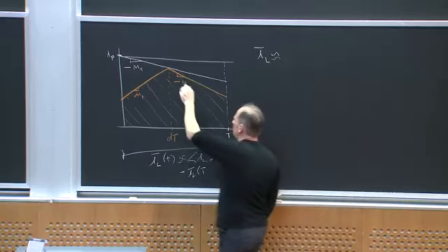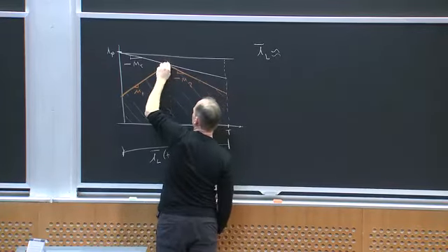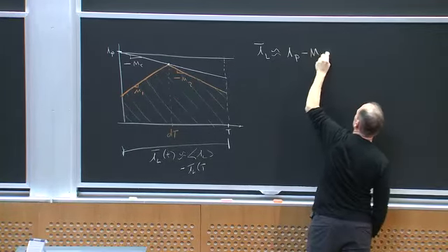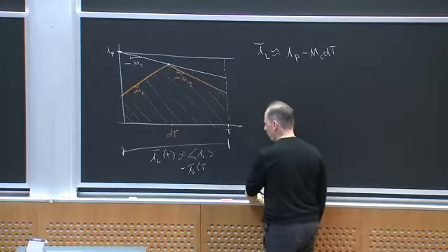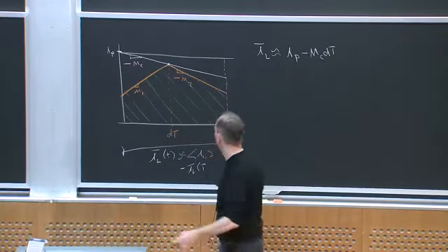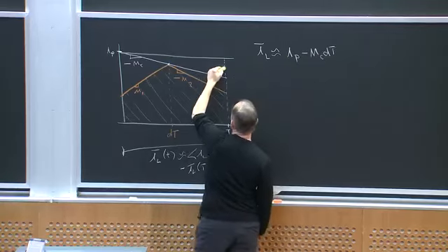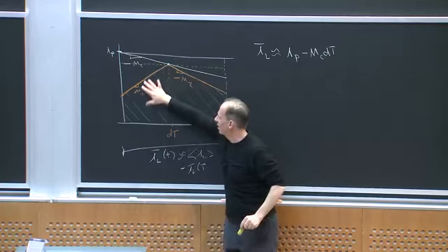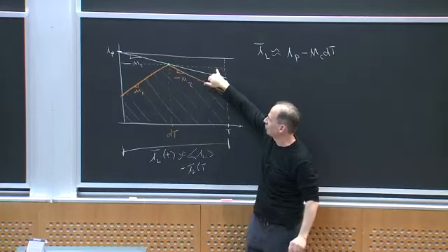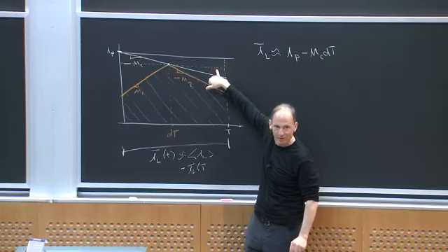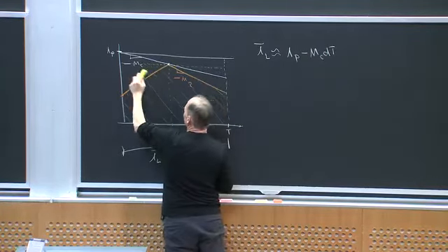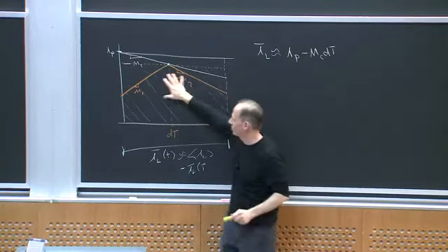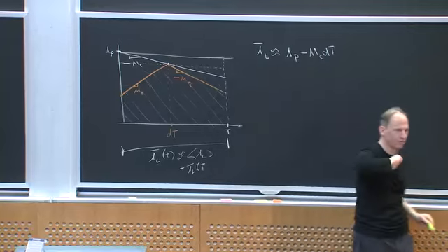Okay, well, let's see. The peak of this waveform here is I peak minus MC dt, right? If I just use this value, that would be exactly the local average in the cycle if the orange waveform looked like this green waveform, right? But what I really need to do is subtract off the average of this area and the average of this area, right? And then I'll have the average underneath the inductor current curve, right?